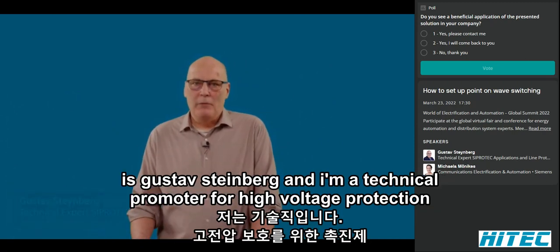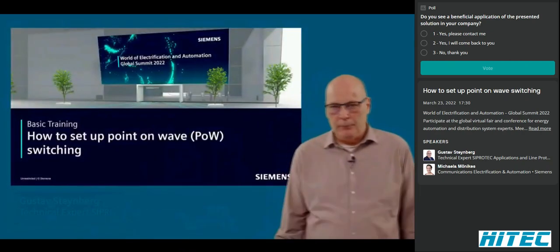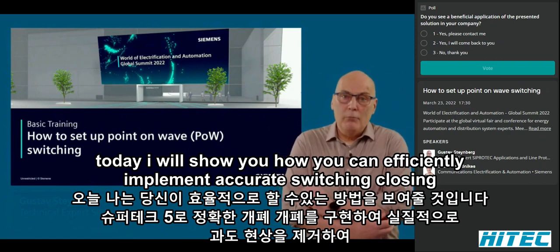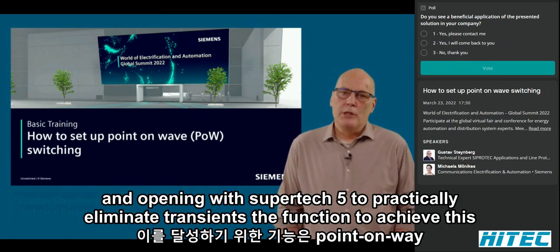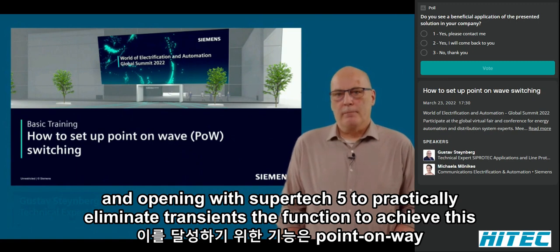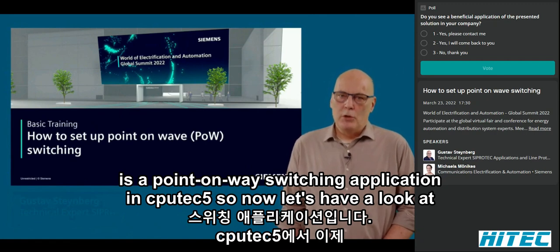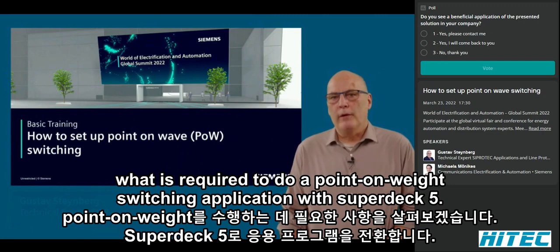As you've heard, my name is Gustav Steinberg, and I'm a technical promoter for high voltage protection. Today, I will show you how you can efficiently implement accurate switching, closing and opening with SIPROTEC5 to practically eliminate transients. The function to achieve this is a point-on-wave switching application in SIPROTEC5. So now let's have a look at what is required to do a point-on-wave switching application with SIPROTEC5.